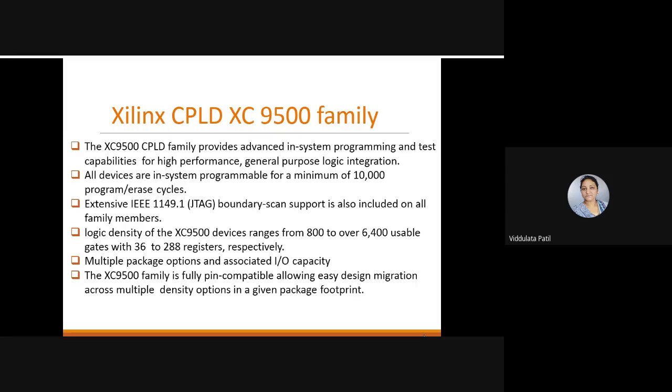And then it has test capabilities for high performance and general purpose logic integration. So this is the most important feature of the XC9500, that it has advanced in-system programming and also test capabilities with high performance. Then, all the devices are in-system programmable for a minimum of 10,000 program or erase cycles.